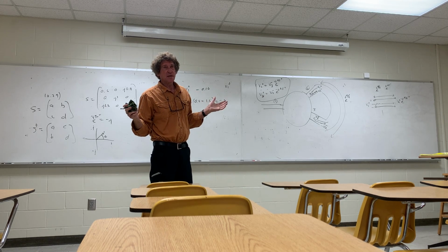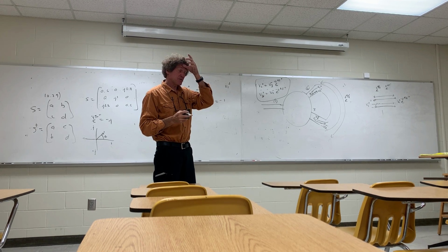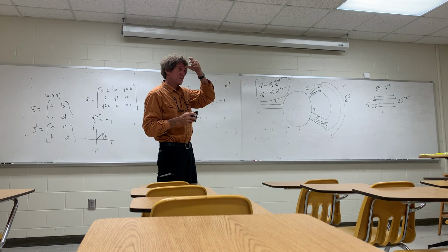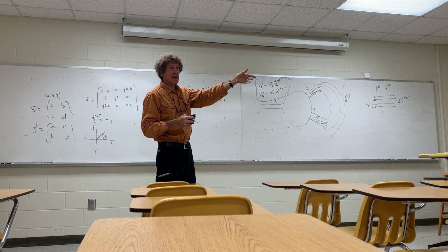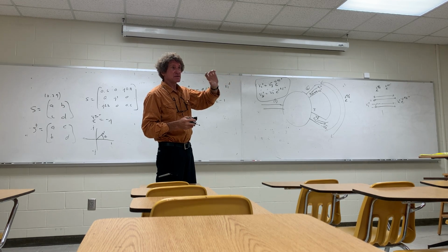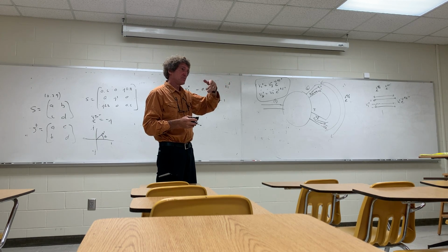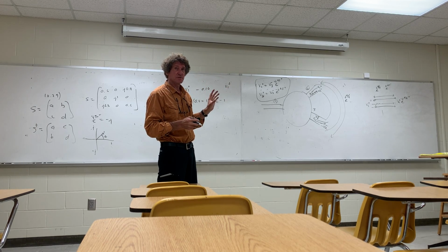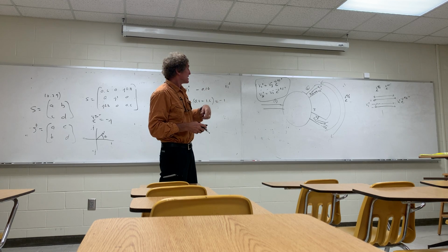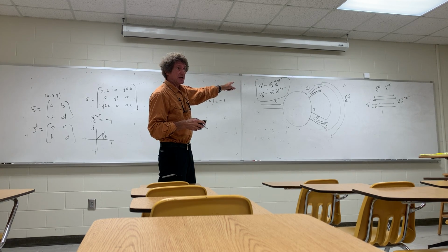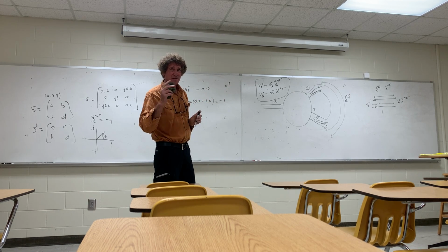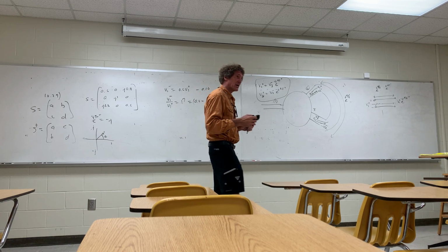It's manipulating those things, and I'll tell you, the first couple of times you do them, it gets a little confusing, but you're always after one thing. You want one equation that has V1 plus, V1 minus, if you're going to do the reflection coefficient at any point, or V2 minus, V2 plus, or V3 minus, V3 plus, if you're getting a reflection coefficient at one of those ports. Do y'all follow me? And you just have to manipulate it. That's the key right there to link what's coming out of one port to what's going into another. It gets to be a little bit of a hassle, but you can figure it out.